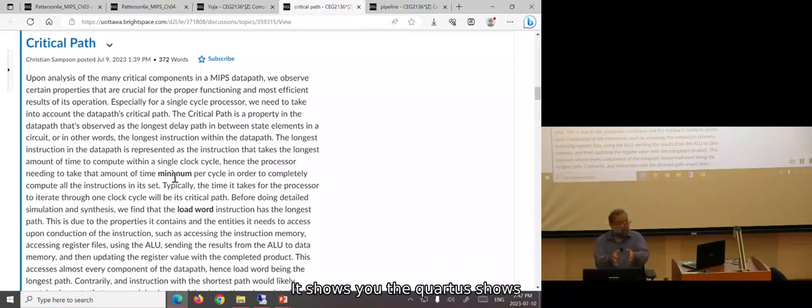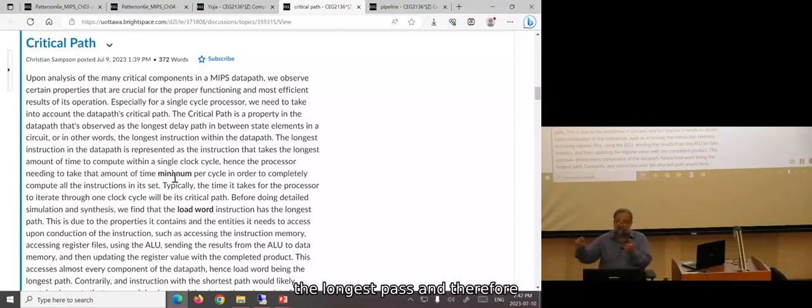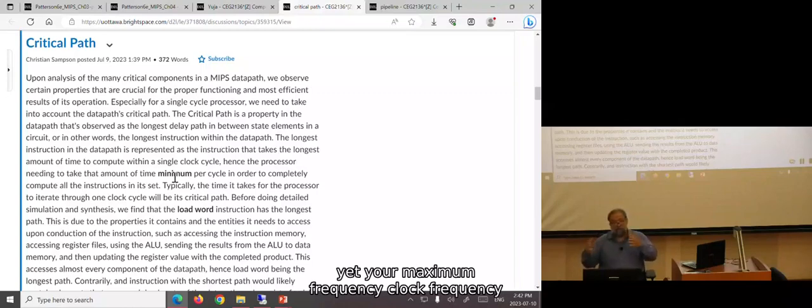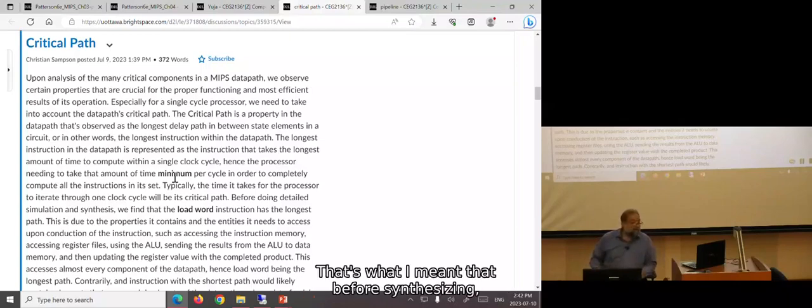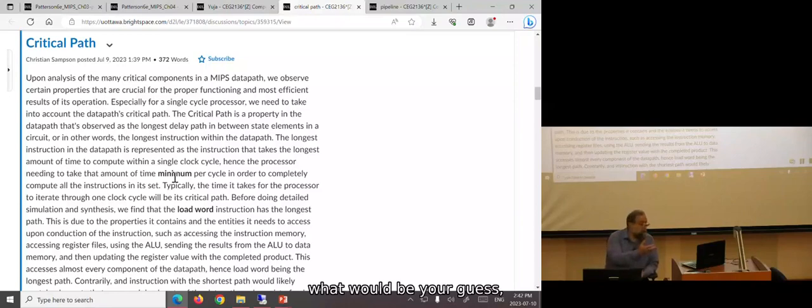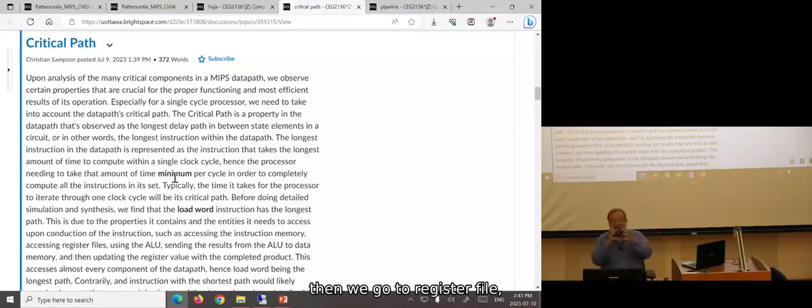Quartus shows you that this path is the longest path, and therefore your maximum clock frequency could be something like this. So that's what I meant: before synthesizing, what would be your guess, which you said is load. Yes, it's good, because in load we have fetch, then we go to the register file, then to the ALU, then to the data memory, then we go to writing back to the...